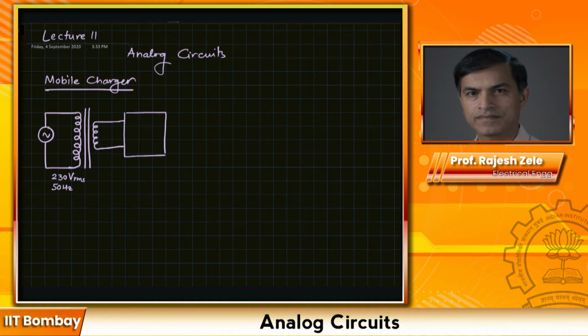So the first step would be to convert a sine wave and rectify the sine wave. Okay, so rectify, I'll explain what that means. So the first circuit that we will go through will be a rectifier. Okay, and this is where we use diodes. Output of the rectifier is generally very noisy, so we use a filter to filter out the noise.